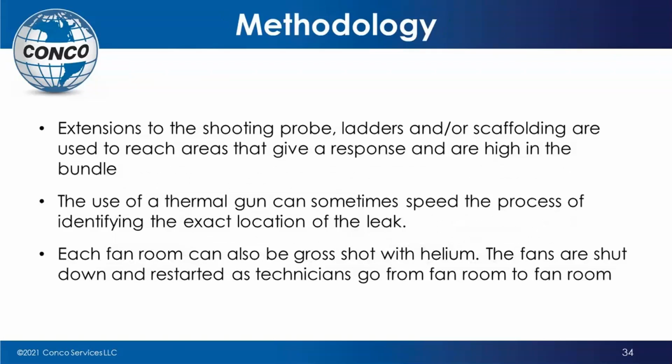So the methodology when we get up onto these units themselves is to get up on the unit, and we use extensions to the shooting probe. We use some ladders. Sometimes scaffolding has to be erected for this because of where we've got to go. But we do have some tools that allow us to reach high up onto that ACC unit so that we can pick the leak up anywhere in that particular bundle.